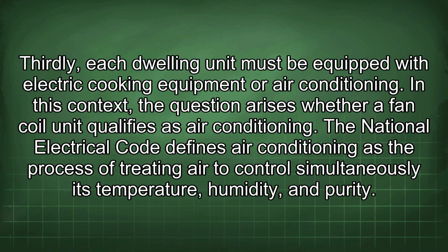Thirdly, each dwelling unit must be equipped with electric cooking equipment or air conditioning. In this context, the question arises whether a fan coil unit qualifies as air conditioning. The National Electrical Code defines air conditioning as the process of treating air to control simultaneously its temperature, humidity, and purity.